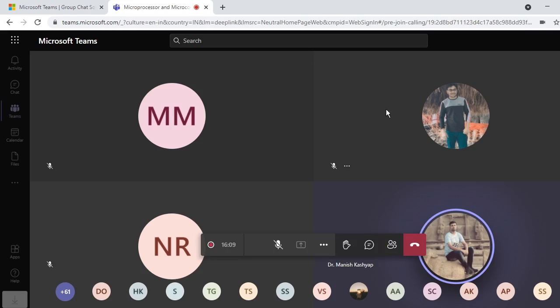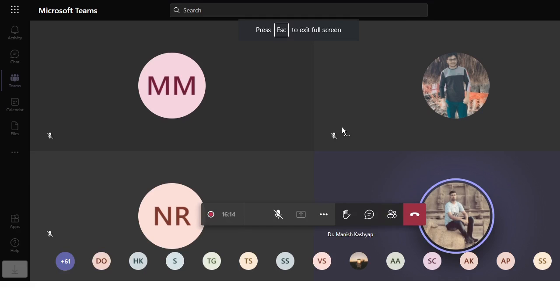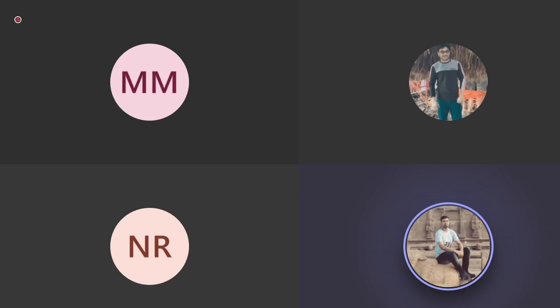So we are now going to study first of all the typical 4 T states, although more or less can be consumed for a particular instruction, which we will see in the laboratory sessions. But typically 4 T states will be consumed for most of the instructions. So we will discuss them first one by one, and then we will see the corresponding timing diagram. Right. So in T1 state, you can guess that an instruction could typically access the externally interfaced memory, or it could not access the externally interfaced memory, right?